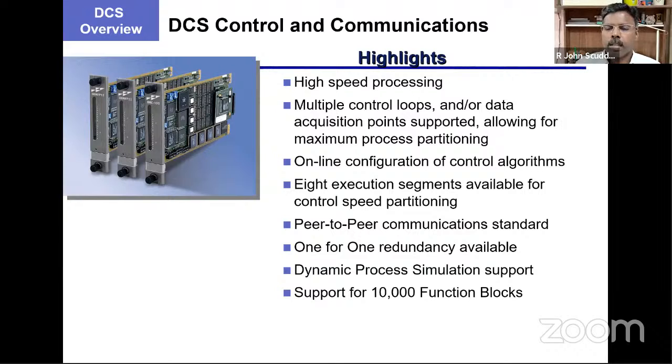At any point of time, if any one network fails, only that particular network fails, but the power plant keeps on running. And that is very important. We request a shutdown, or whenever there is a shutdown, we immediately replace all the faulty things and try to rectify those problems. Now, inside this BRC, all our engineering logics are stored. As such, you do it in a computer. Once the project is completely designed or engineered, the entire logic of the project has to be stored into a controller, the heart of DCS, which is the processor.